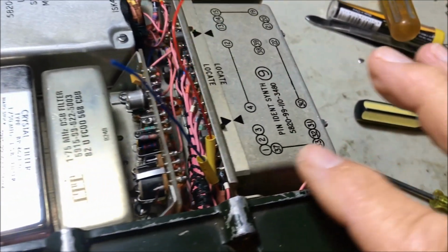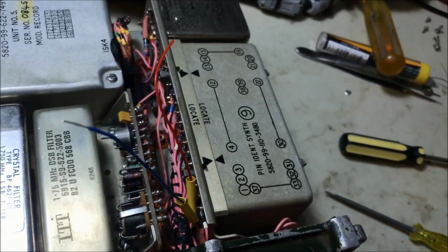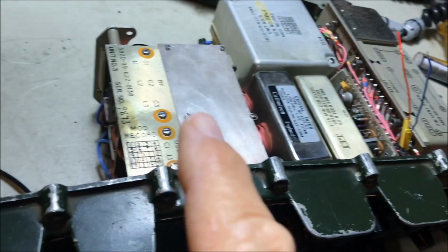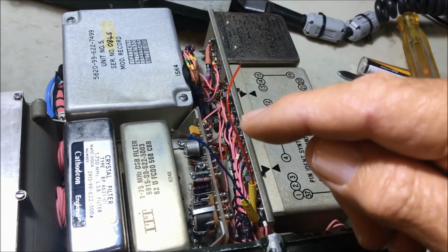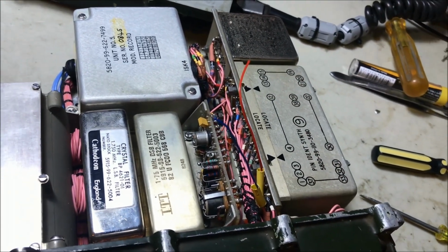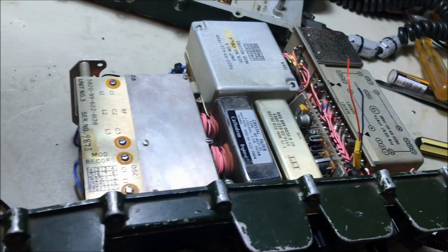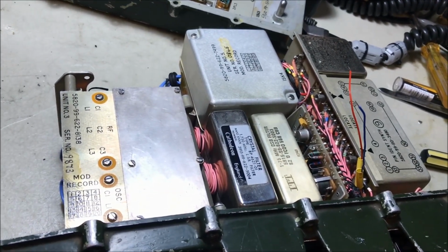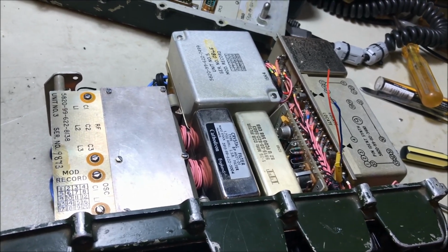Right, I've managed to do the intricate soldering job. I've soldered the little blue wire going over here to the 3A and 3H board, and I've soldered the red wire onto the synthesizer. So what we're going to do is put it all back together again. We'll get the radio operating back as it was before, and then we'll see about disconnecting that and injecting the separate DC supply in and see the results of our test.